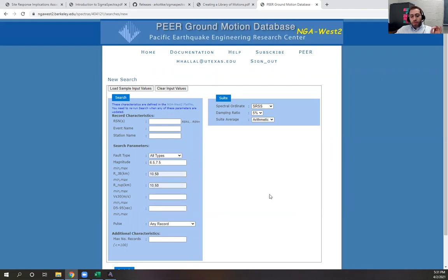And then another critical parameter is Vs30. To put things into context, you have developed a design response spectrum, I believe in your case it was for site class B, rock conditions. So that is one. Two, this design response spectrum is consistent with the conditions at the site you are investigating.